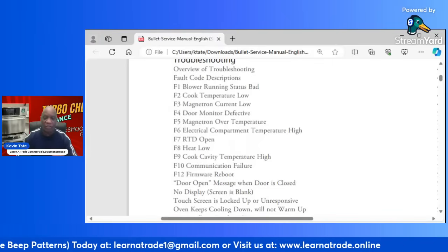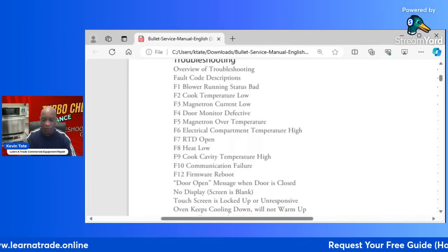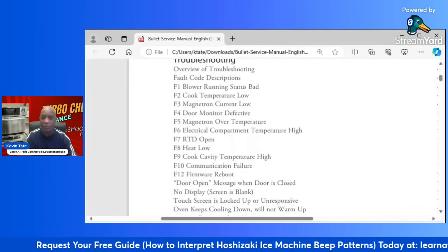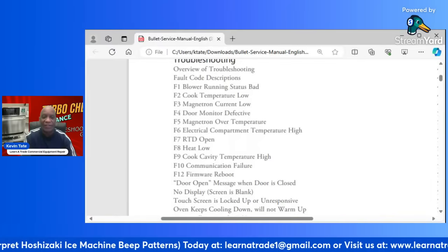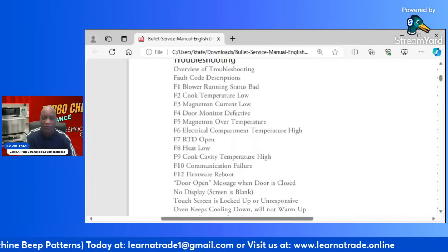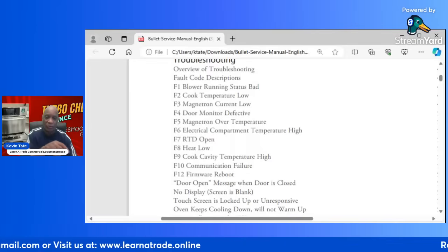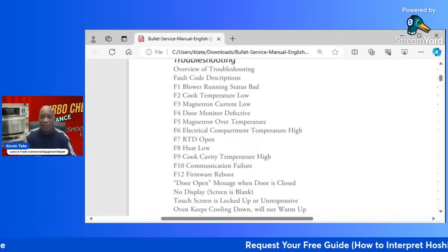And what's connected to that high volt circuit is a 20 amp fuse. So that fuse is right on that right side also, just underneath the relays. Sorry, I lost my train of thought there. But on the older models, it'll be right on the right hand side. On the newer models, your relays will be up top, and your fuses will be just to the right side of the board on top, along with the relays.